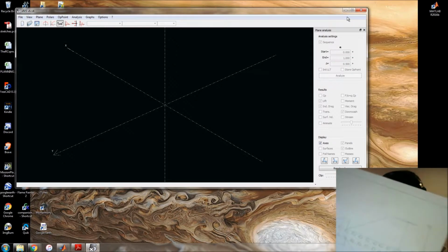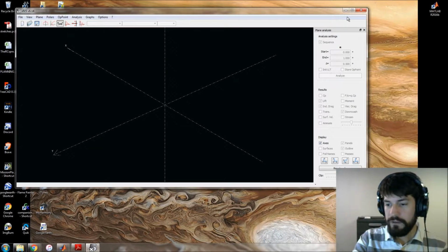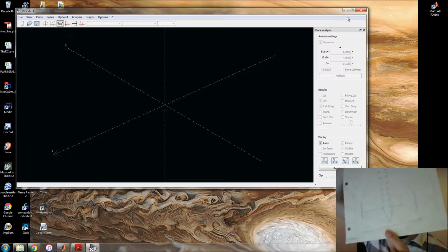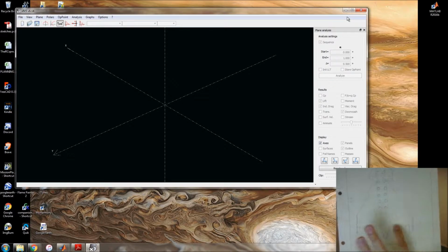I drew out, this is kind of modeled after the Viggen, which is a European fighter. It's just a delta aircraft with a canard. What I did for this sketch is I just started with some actual distance, like I wanted the wingspan to be 1.2 meters. So I drew out 1.2 meters and then drew the whole plane off of that bottom trailing edge line. It just happened to work well for this design.